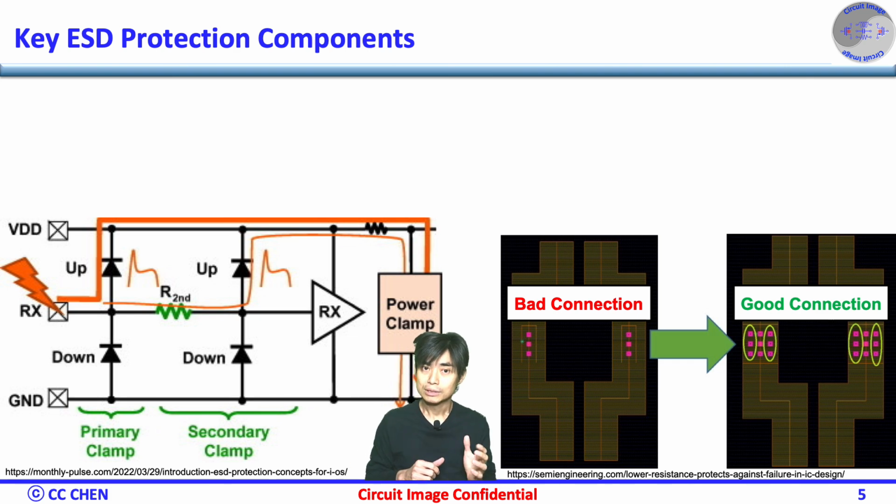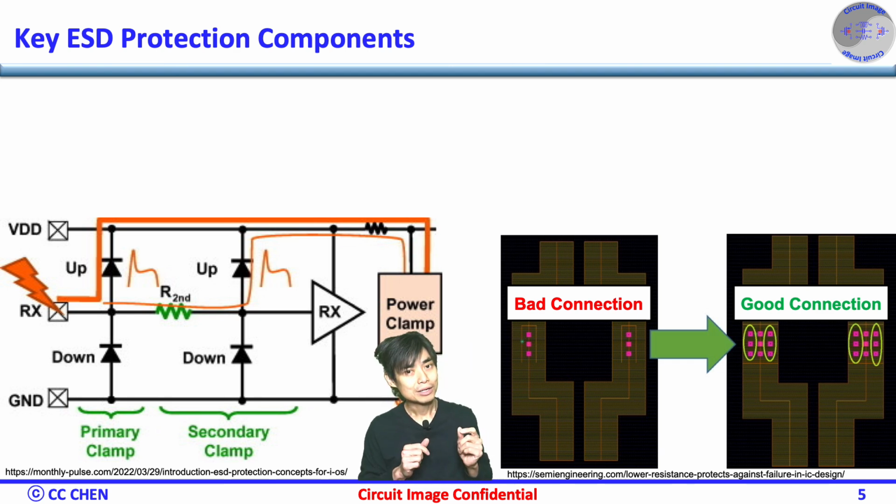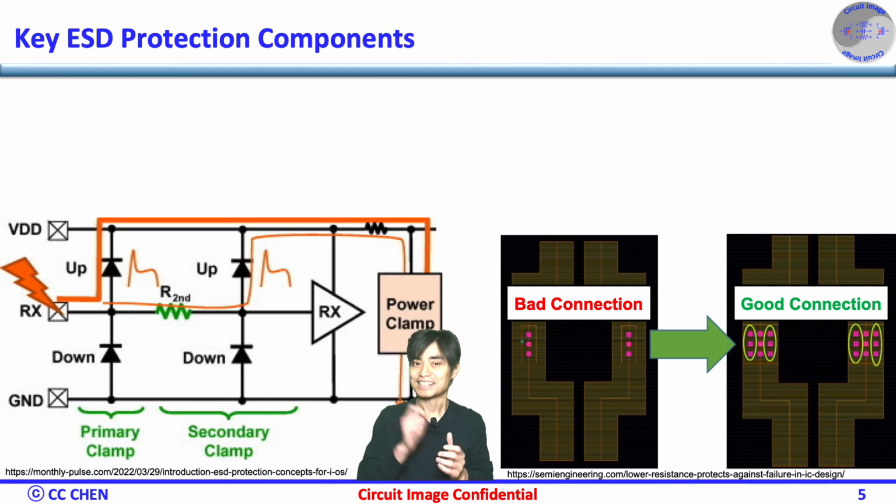Rail-to-rail protection is common for digital circuits, while analog designs need customized approaches. Pad-to-ground structures help in low-power applications, where leakage is a concern. Internal protection ensures sensitive transistors are not exposed to high voltage.